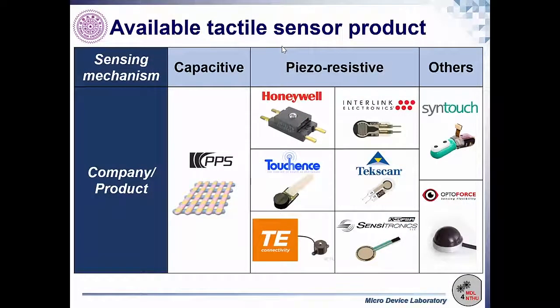This is a brief summary table of some available force sensor products. They can be divided into 3 parts due to different sensing mechanisms, and from the point of view of different fabrication processes. To take further advantage of tactile sensors, miniaturization is an essential approach to integrate them more easily into your target system. So MEMS technology is utilized for the needs of high sensitivity and high capacity reliability. From this summary table, only 3 of them are fabricated using the MEMS process. The other feature that needs to be emphasized is that they all need to be integrated with a micro-tactile bump to effectively apply the force.